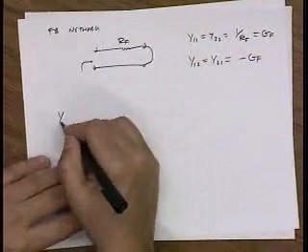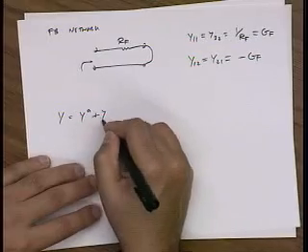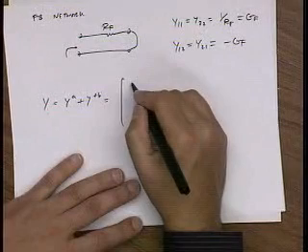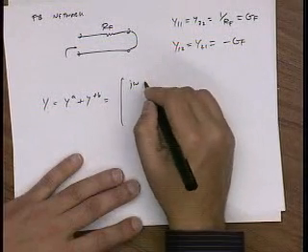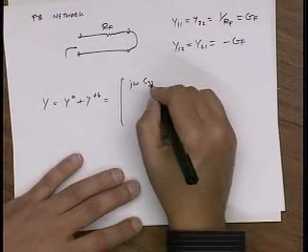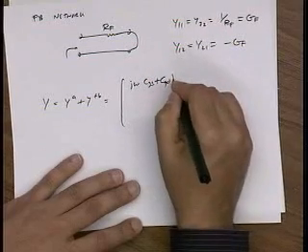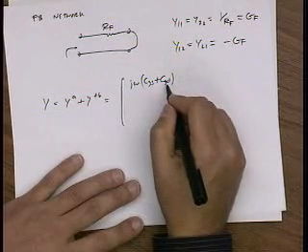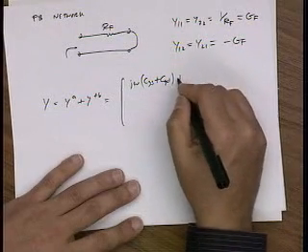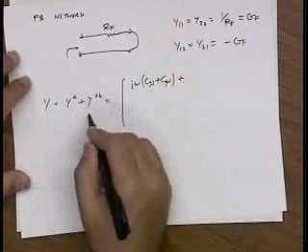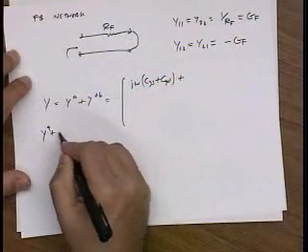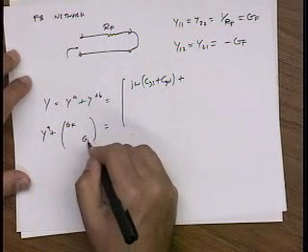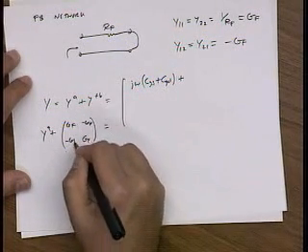So then the total Y parameters, which is the Y of the amplifier plus the Y of the feedback, is as follows. Remember, Y11 is the input, it's Y pi, which is, in this case, let's say it's a FET, C GS, plus Y mu, which is j omega C gate to drain. So let me just write this as Y amplifier plus GF, GF, minus GF, minus GF.